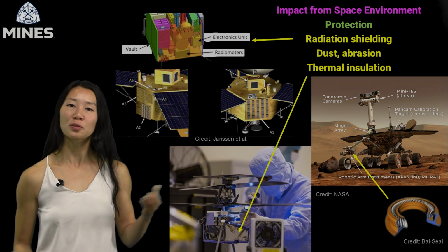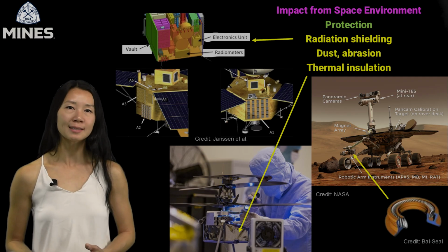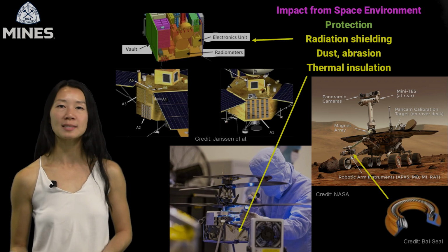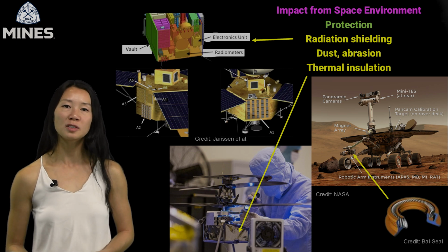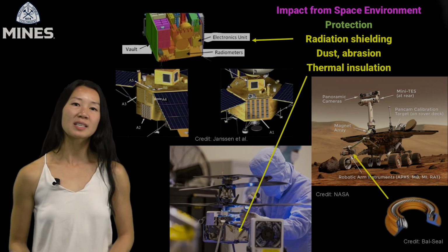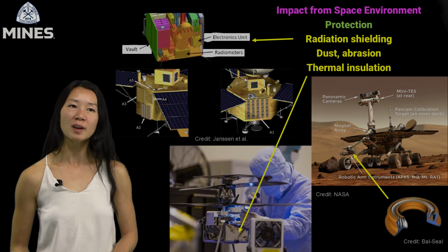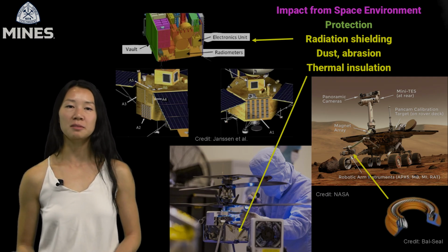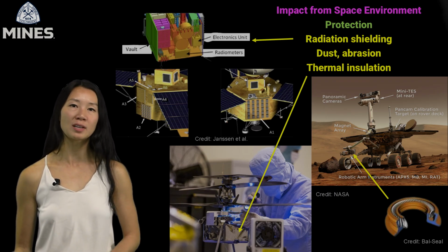And finally, we use thermal insulation to survive the cold. Here, you'll see a NASA technician integrating insulation onto the Ingenuity helicopter, which operates in Martian nights that drop below -100 degrees Celsius. Its electronics are housed in a small silver box called the HWEB, or Helicopter Warm Electronics Box. This box uses Kapton heaters and a metallic Kapton film to both absorb solar radiation and trap heat inside the avionics compartment. Whether it's shielding from radiation, sealing out dust, or retaining heat, the Structures and Mechanisms team is responsible for building the physical buffer that keeps the rest of the spacecraft safe.